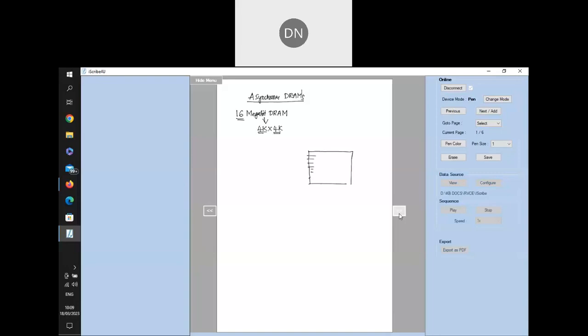The number of rows present is 4096, and there are 4096 columns as well. The chip provides an 8-bit bus, D7 to D0. That means at a time I can read 8 bits. That is why they have grouped the 4096 columns into 512 into 8. If you multiply 512 by 8, you get 4096. That means in every row there are 512 bytes available. Any one byte of the given row, I'll select and pass on.